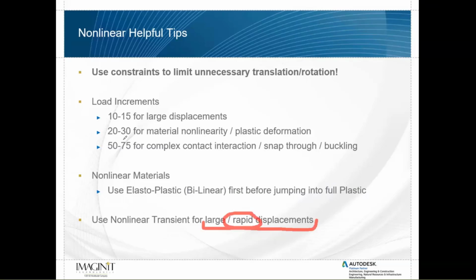So first thing you should try is to bump up your increments. But if that doesn't work, I recommend jumping to a nonlinear transient analysis, which is going to be time-based instead of using load increments. So you'll be applying a time step, so it's time-dependent, and it's going to be a much more accurate solution. It may take a little bit longer to solve, but it will help to capture that rapid displacement with more accuracy than a nonlinear static solver will.